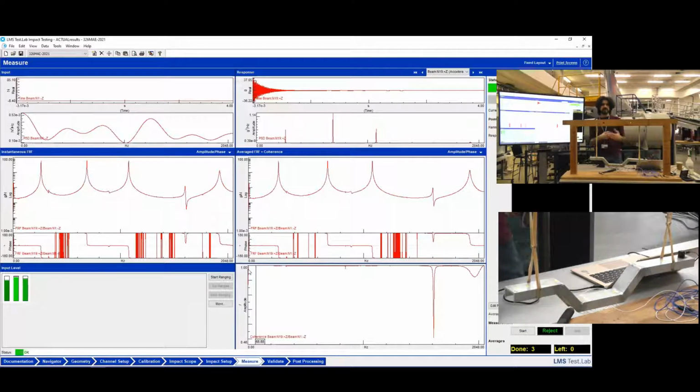So this thing I'm not capturing, I'm not recording these. I'm only recording my strikes. So if I do both at the same time, the accelerometer will pick up the vibration of both the hammer and the music, whereas the signal box, the acquisition box, will only capture the hammer. So the coherence will be low because not everything that we captured from the accelerometer came 100% from the hammer.